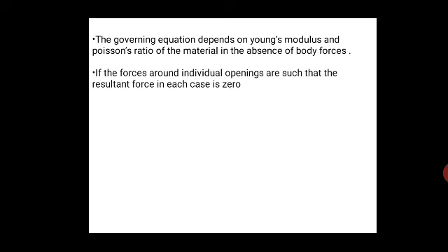Otherwise, Poisson's ratio has only a small effect, even in the case of multiply connected bodies. So in these conditions, also if the forces around individual openings are such that the resultant force in each case is 0, then the stress distribution remains independent of the elastic constants. So it is possible in most practical cases to apply the photoelastic model result to the prototype.